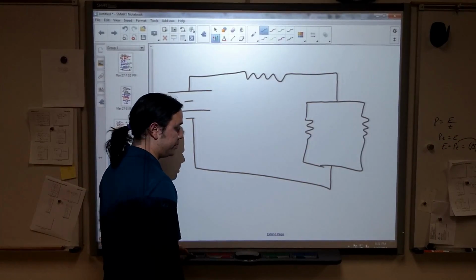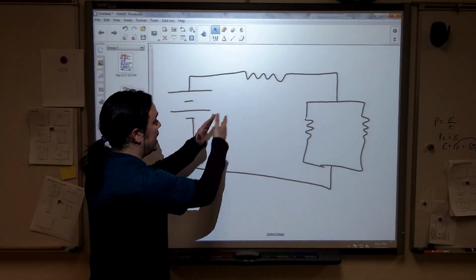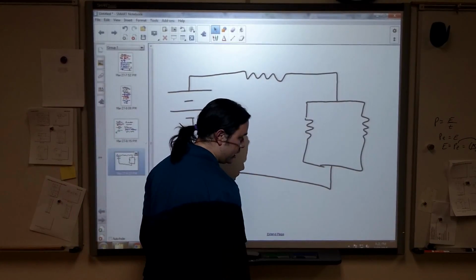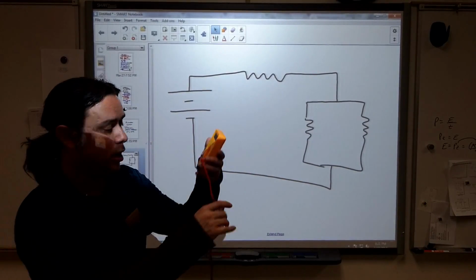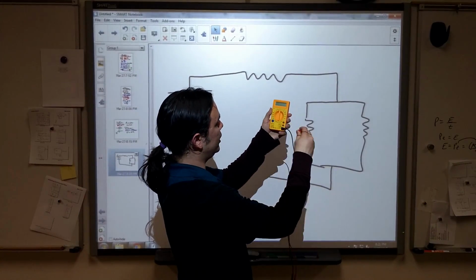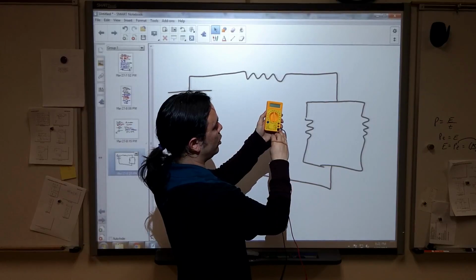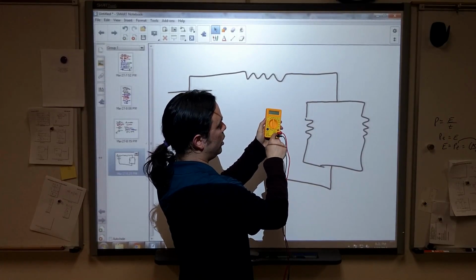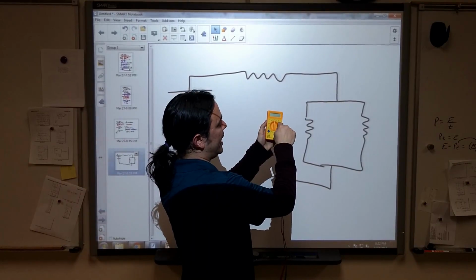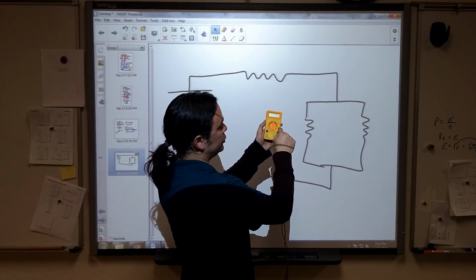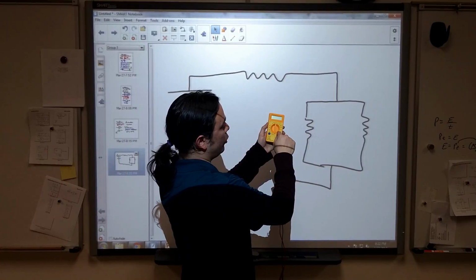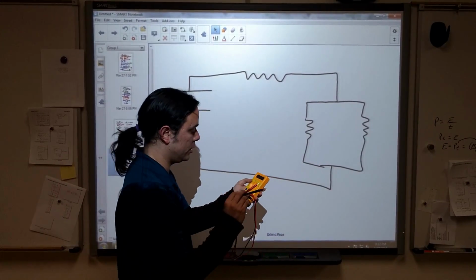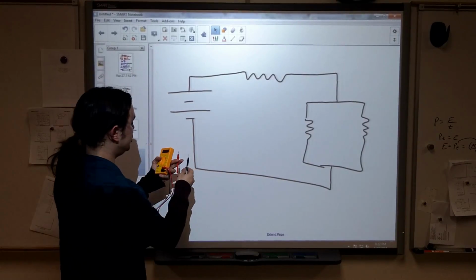If you want to measure the potential across a component, for instance across the battery, on the regular DMM in class we have our common port down here. The black cable goes in the bottom, and the red cable goes in the middle one for both the voltmeter and the direct current amps, all the way up to about 1 full amp. Technically, it maxes out at 200 milliamp.